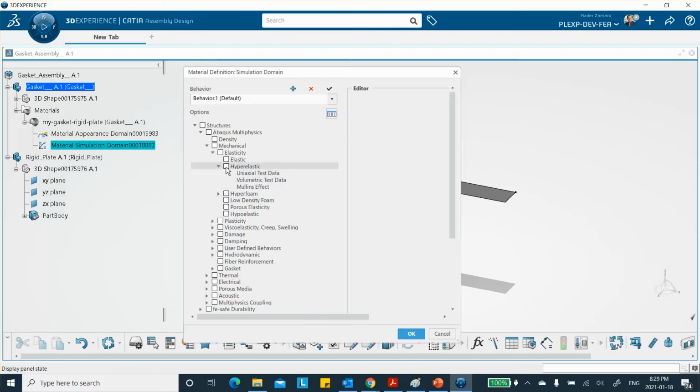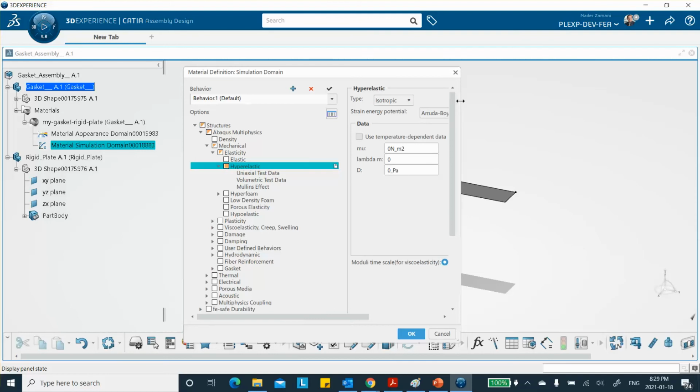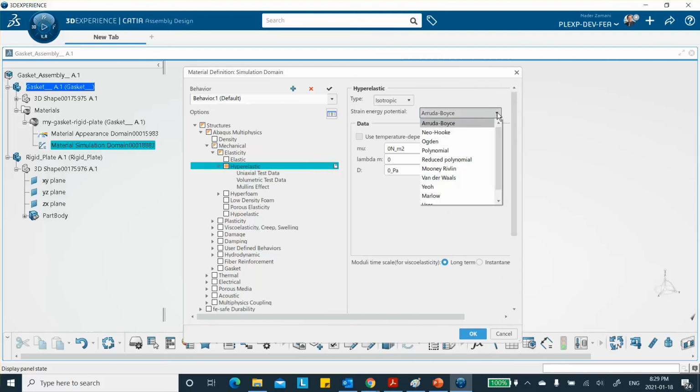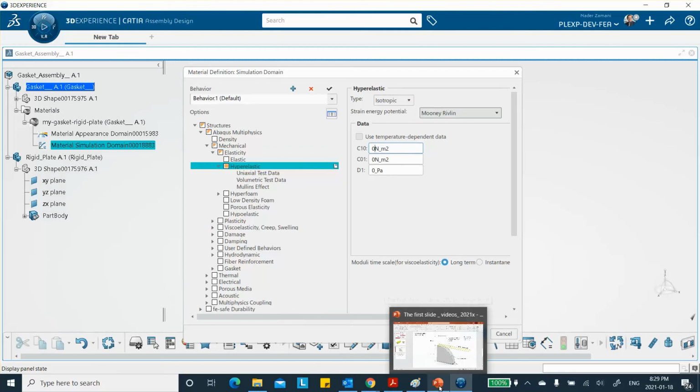Okay, and if you check this hyperelastic box, it will say, okay, what kind of model would you like to use? Well, in here there is a Mooney-Rivlin material. Pull it down, Mooney-Rivlin material, and you put your C1 and C2 directly in that box. Okay, so let me see now. C1 and C2. Let's see what they were.